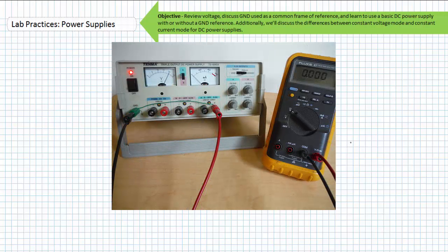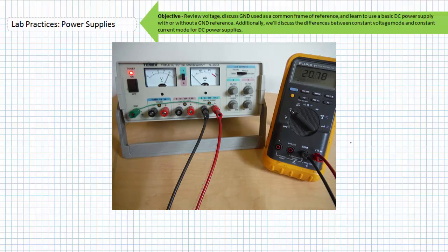Now, let's try a positively grounded DC power supply. In this case, the positive lead is tied to ground, and there exists no differential between the positive lead and ground. However, there still exists a positive 20.78 volt differential between the negative lead of the source and the positive lead when the negative lead is used as the reference.